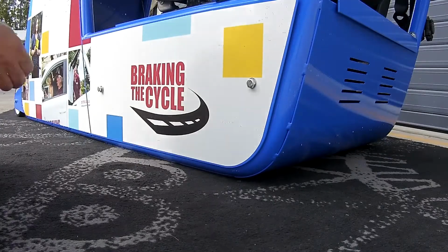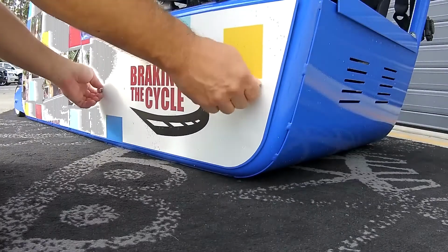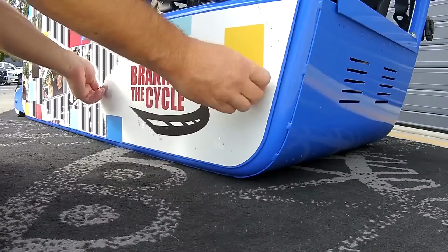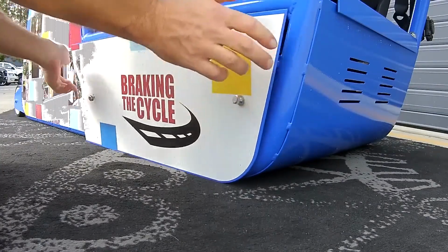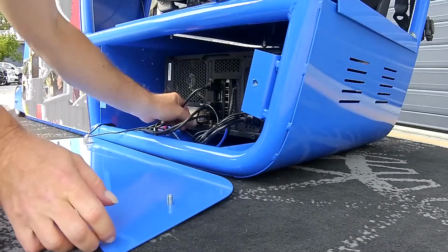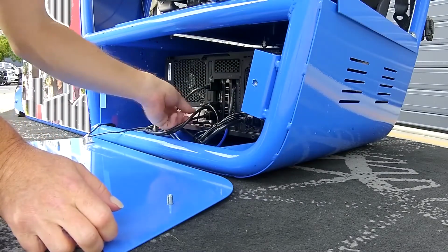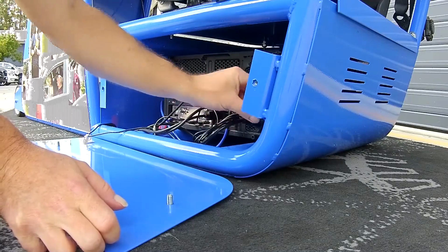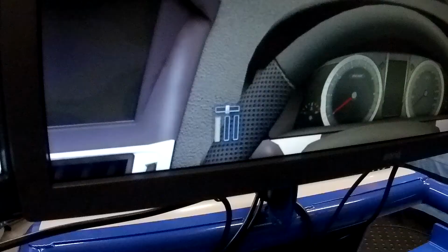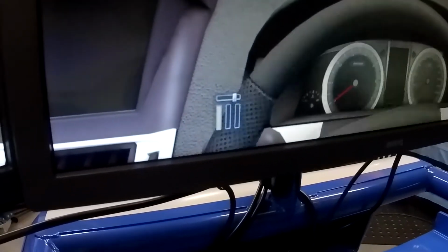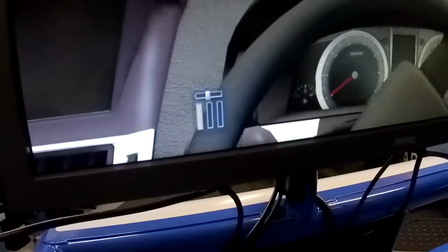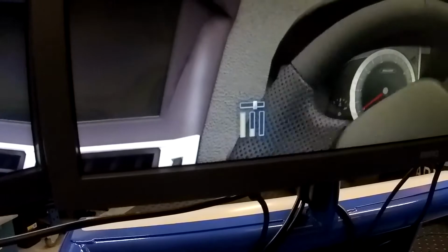Likewise, the USB to the computer might be loose or the USB port might be disabled. So remove the side panel to check the connections and/or move the USB cord to another USB port. When you connect the USB, you should hear a Windows sound for a new connection. When driving in the simulator software, when you press the pedals or turn the steering wheel, there is this controls indicator on the middle screen that registers if the feature is working. So you can use this to check and see each pedal and the steering wheel use being registered here.